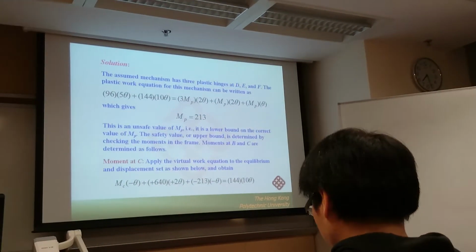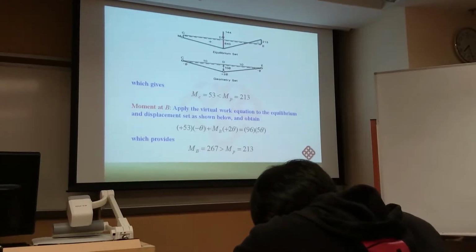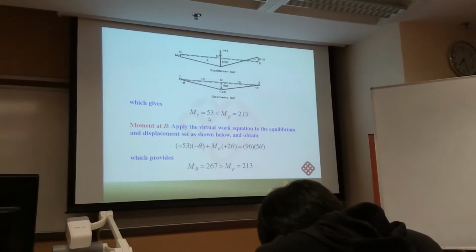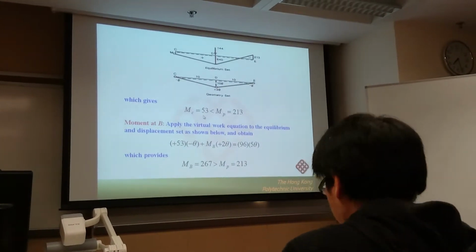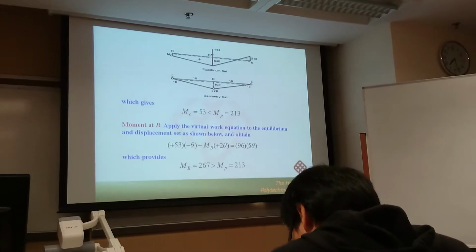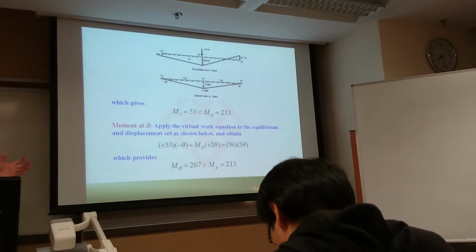So here is the result for the moment we obtained. From this equation, the moment we obtained is equal to 53. It is less than the plastic moment, so the moment check is satisfied. But that is just for section C.